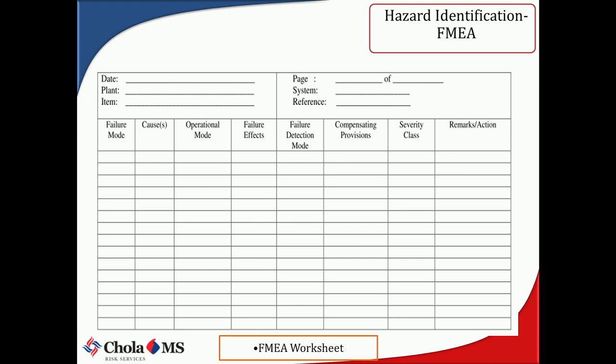Okay. Now, what happens here is that you look at the failure mode, in terms of that particular failure that has happened. What is the cause of that failure? The operational mode: which particular state of operation is it operating in?